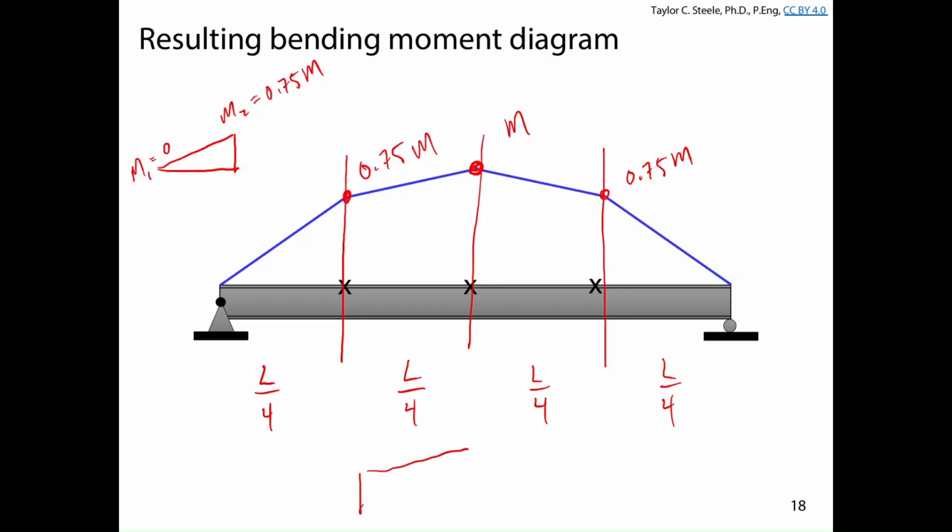And in the middle 2 segments, we have a symmetric situation where M2 is equal to M, M1 is equal to 0.75 M. So this is even more clear, at least I would hope that it's more clear, that this is going to be the more critical segment, and it's going to be the more critical segment for 2 reasons. One, the moment on the section is actually higher, right? The maximum moment on the middle segment is bigger than the other ones by about 1/3.